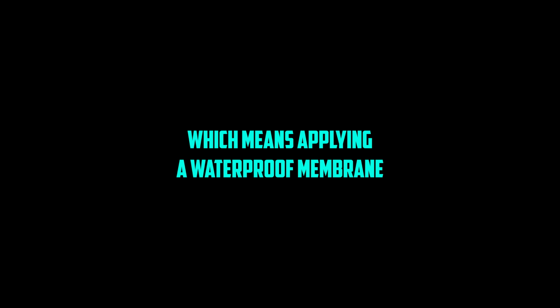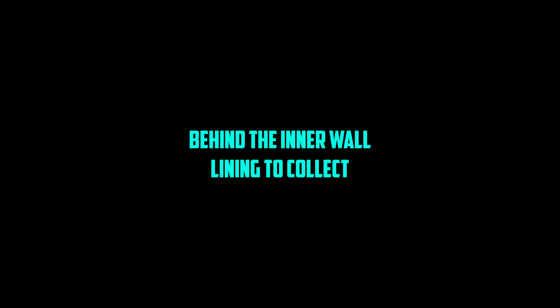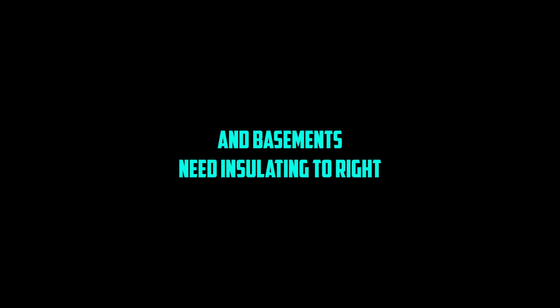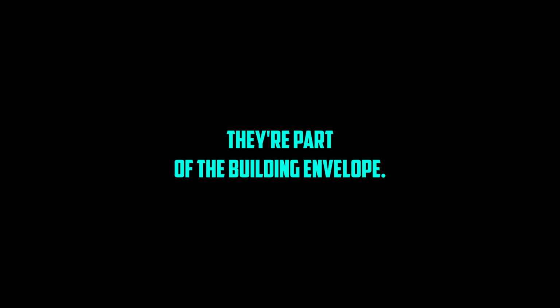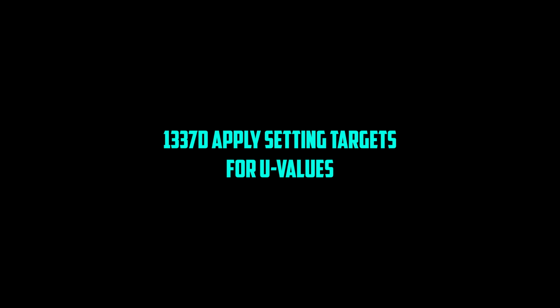Tanking, which means applying a waterproof membrane like asphalt or plastic sheets, either inside or outside. And drained cavity systems, which create a space behind the inner wall lining to collect any penetrating water and drain it away safely. And basements need insulating too, right? Thermal performance. Absolutely. They're part of the building envelope, so building regs Approved Document L and standards like BS EN ISO 13370 apply, setting targets for U-values to limit heat loss.